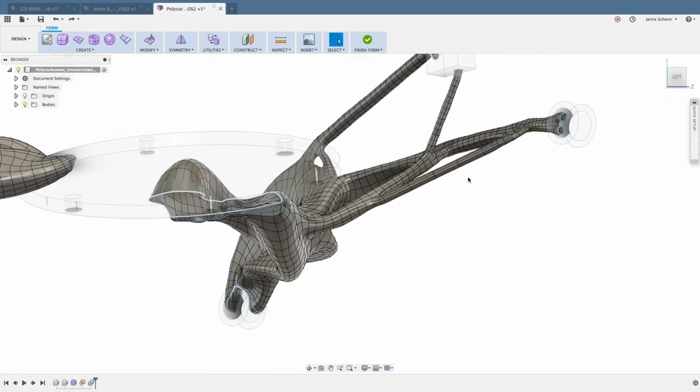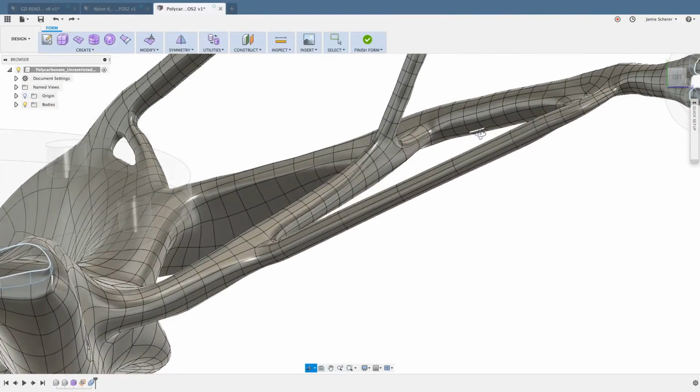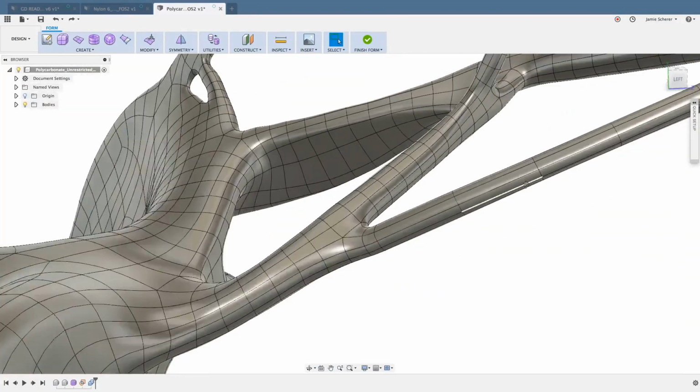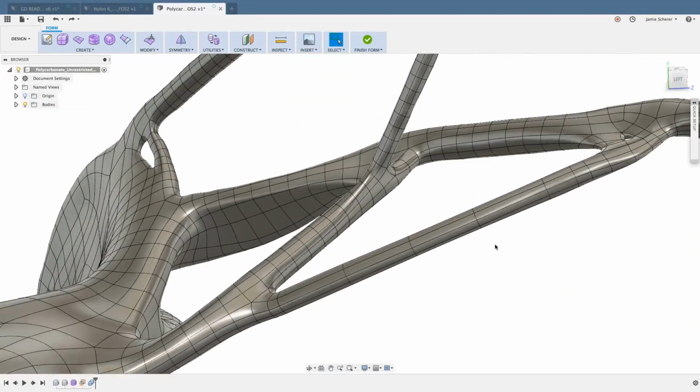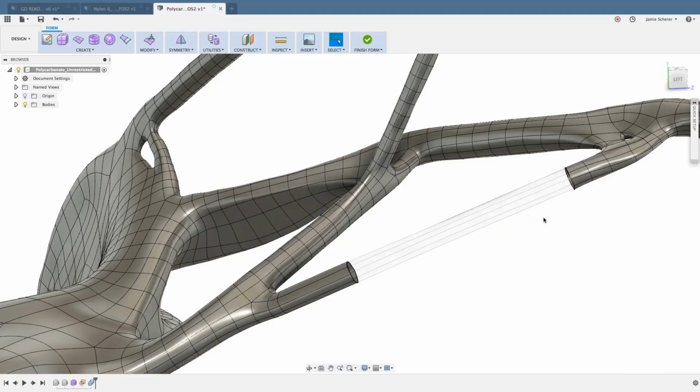Let's get back in a perfect left view over here. There we go. And I'll make sure to be a little bit more careful this time and just grab the transitions that I want. All right, so now that I've grabbed and hopefully deleted just the ones that I want, again, I could have fixed those or patched those edges. For simplicity's sake, I just want to leave these two open edges.